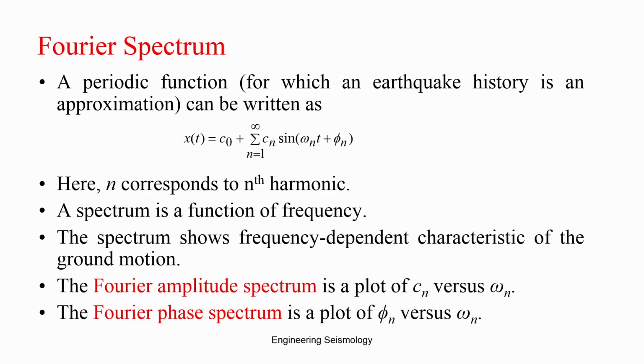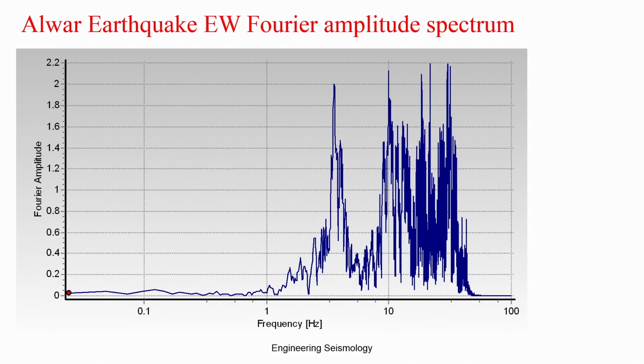The Fourier power spectrum is given with the natural frequency of the system, where you can see the angular frequency values. So this plot will be generated, and that plot is called a Fourier spectrum. Okay. This is the typical Fourier spectrum for the different natural frequencies. For the lowest frequency you can see that the displacement amplitudes are constant. For the higher frequency the accelerations are constant, and at intermediate frequency the velocities are constant. You can get a smooth curve of this, where you will see those constant kinds of things. Okay. So this is how you will get a Fourier spectrum.